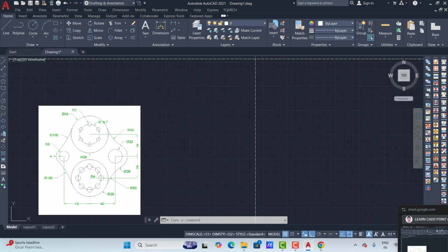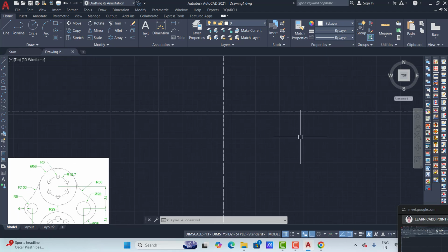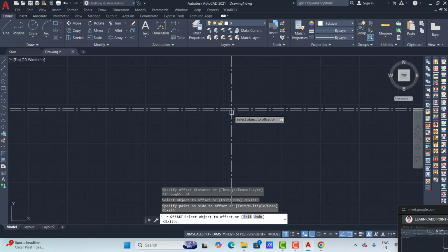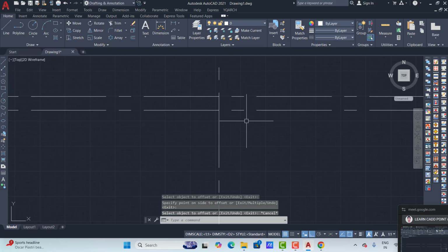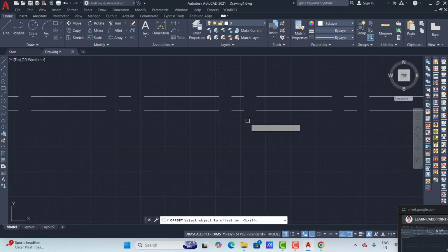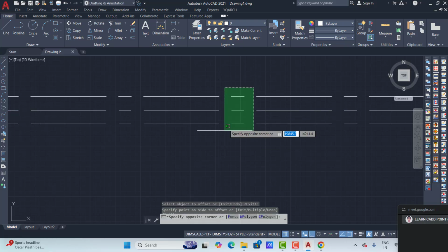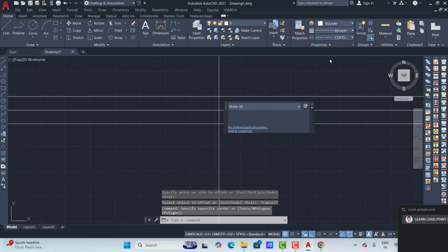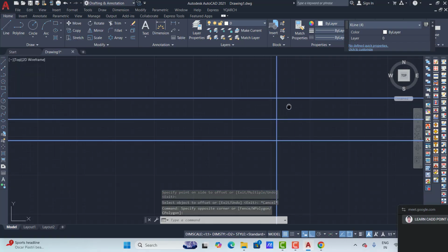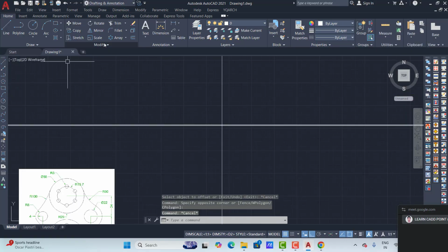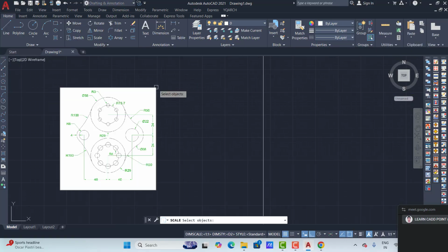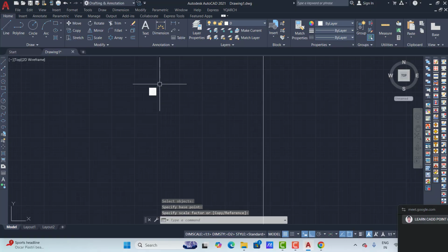Okay, this text size is too much. So again you go D enter, again go modify, and the text height we can put here 5 mm. And arrow, suppose I take single stick, this one I put here 3 mm. And done. Set current, close. So this one again manage. Okay. So click and this will manage, shift. So this is a proper managed dimension.